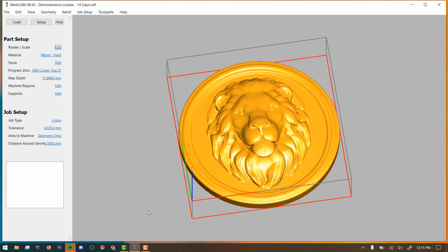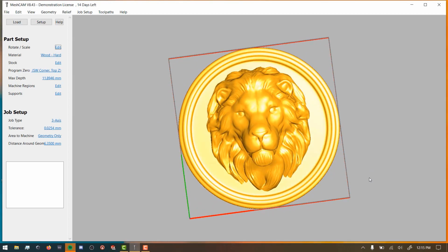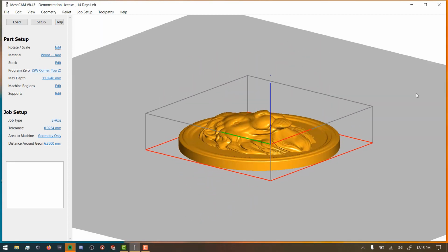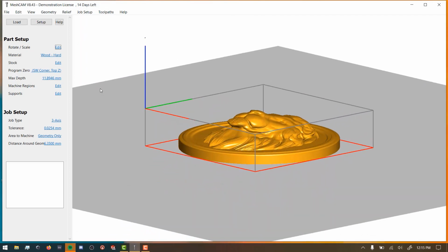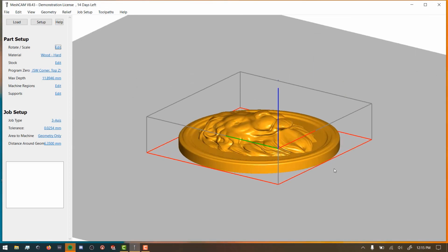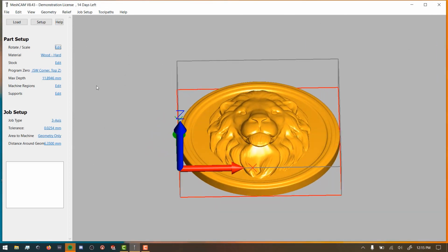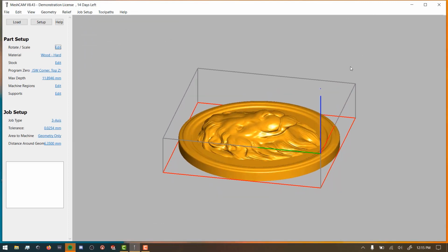And we can see that that has flattened it, right? And that's going to be a lot easier for us to mill because it's more of a flat surface, and our tool depth isn't going to be too extreme there. So I'm really liking where this is going here. And I have now completed importing an STL and scaling it to the correct dimensions.